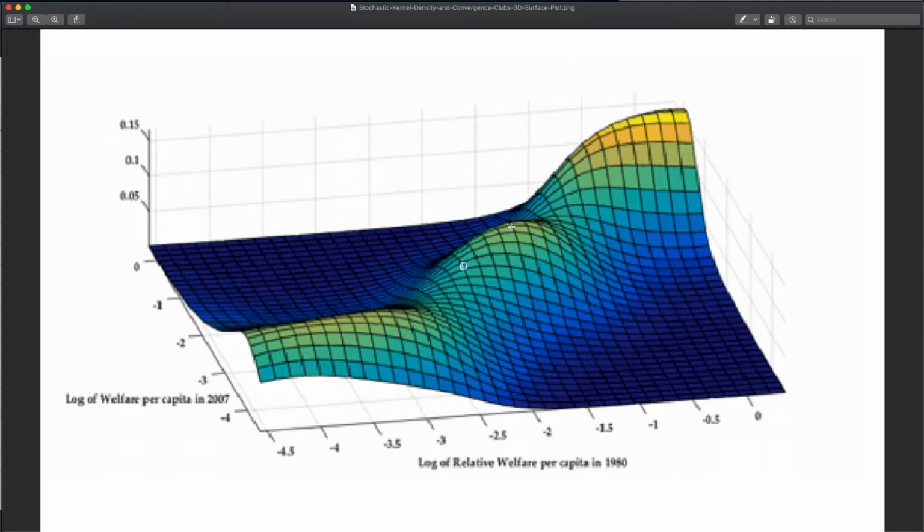We've kind of zoomed in on that iteratively, playing with one variable till we find a relative peak, another variable till we find a different peak, another variable, and then back to the first, and you keep zooming in until you follow this ridge up to some peak. Now that may not be the optimum for the whole design. There may be another peak over here somewhere, but at least that gets you into one.